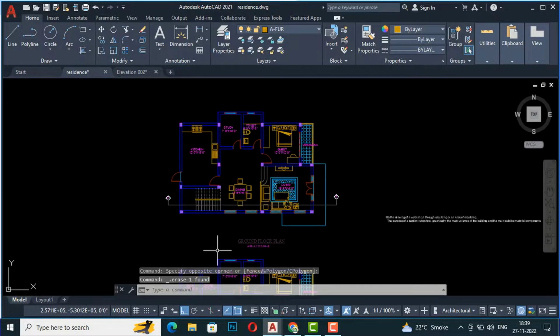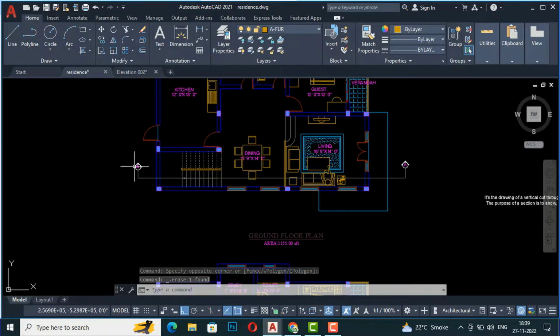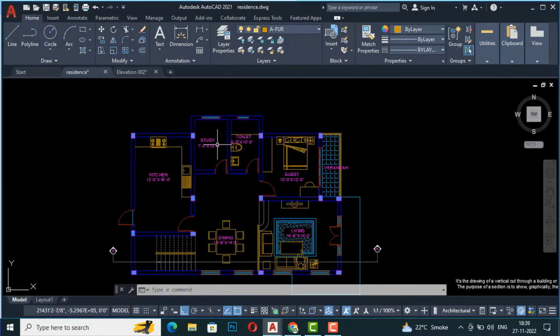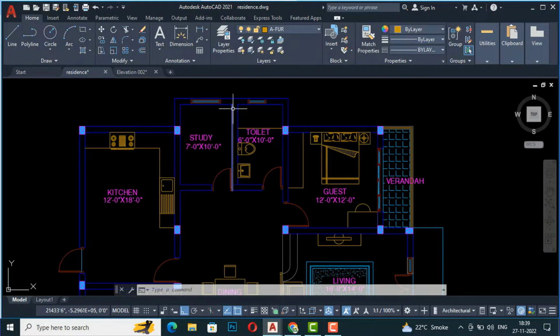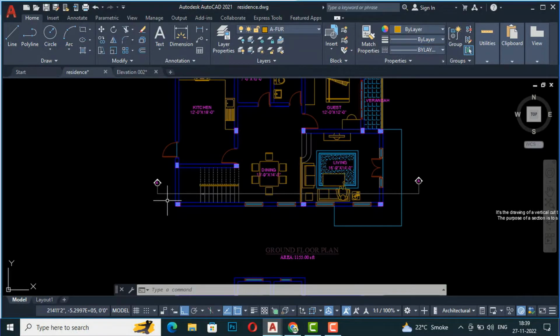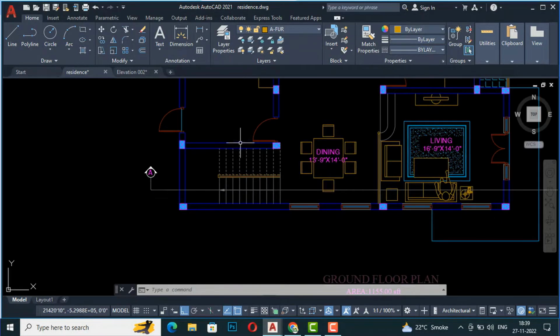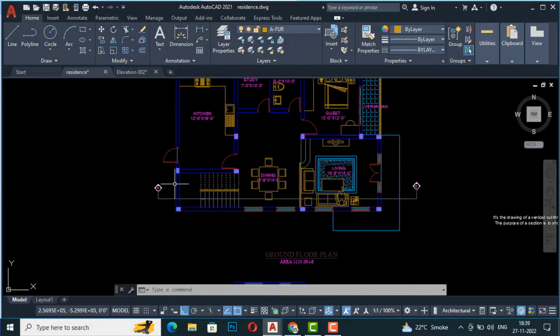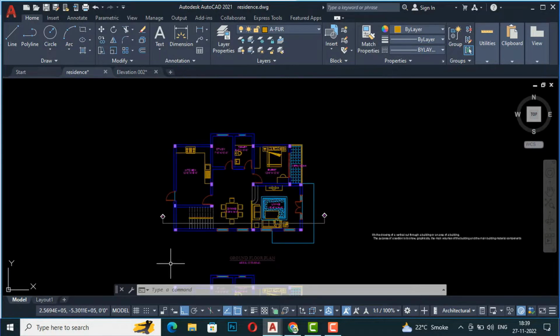This is the staircase cutting through. In a section you will show the complicated parts like a staircase, or a toilet area where you are required to show the sunken slab. You will cut the section through that. The staircase is an integral part of the design. So I am going to draw my construction line, which will be vertical.